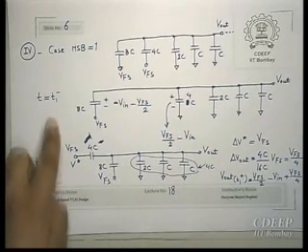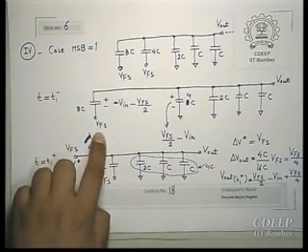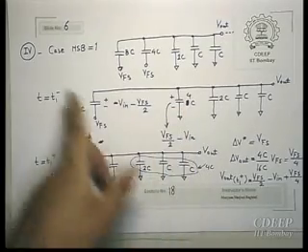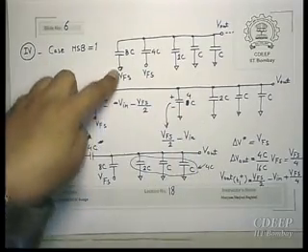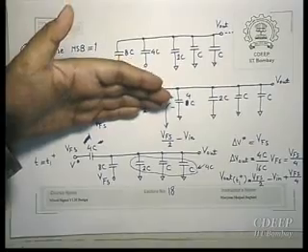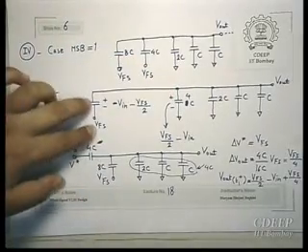So when I consider the initial condition, I consider the bottom plate of AC is connected to V full scale. Therefore, the initial condition that we have is after charge distribution by connecting the bottom plate of AC to V full scale. So now this is the initial condition for the next phase. Therefore, there is no change.